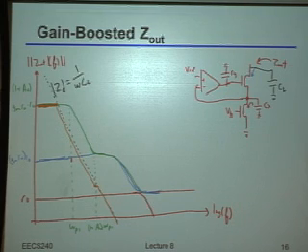Okay? Now, notice that this green curve here, once I hit the gain bandwidth of the amplifier, right, it actually started having sort of a higher impedance, right? It actually had a 0 right at this point. Okay? Well, if I've got a 0 right at that point, and it basically starts flattening out, that implies that you would actually see a 0 in the overall impedance as well.